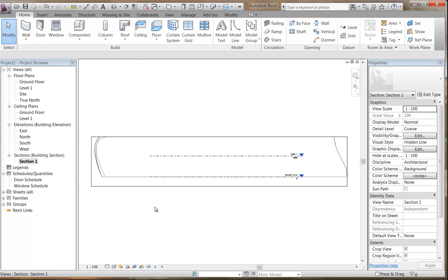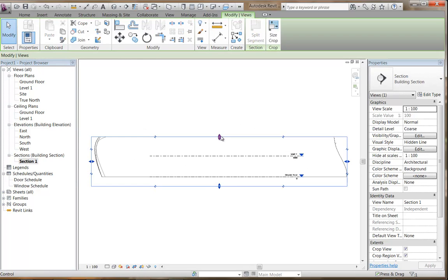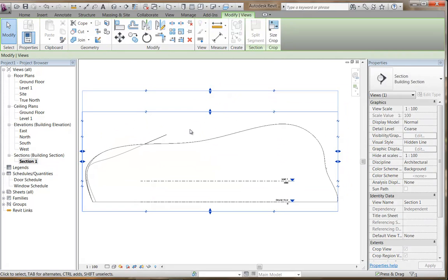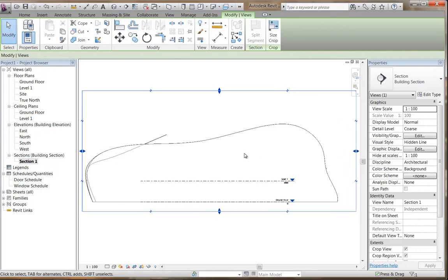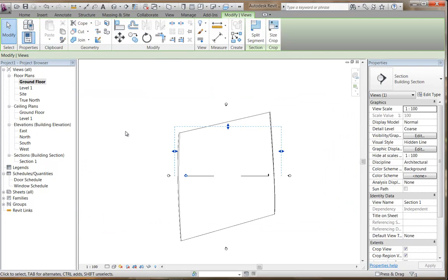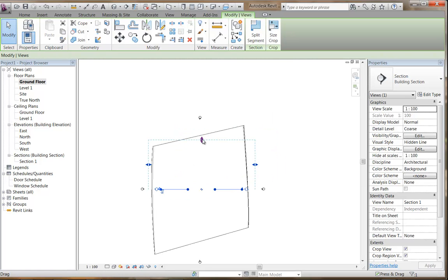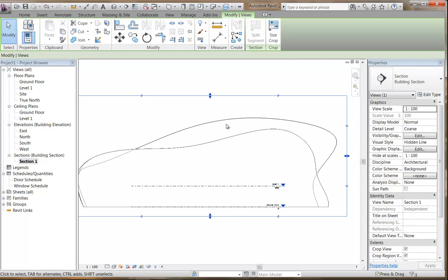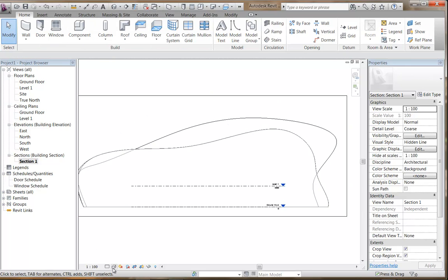Section should be cutting through. It's a bit small, but you can kind of tell there that it is cutting. It's going to be clearer still if I fix it up by making the section box there, or the extent of the section, encompass the whole building. So it wasn't deep enough, but now it will be. In a shaded view, that'll be even clearer. But that's still a mass. It's not a building yet. It's not walls. It's not anything. It's a mass.